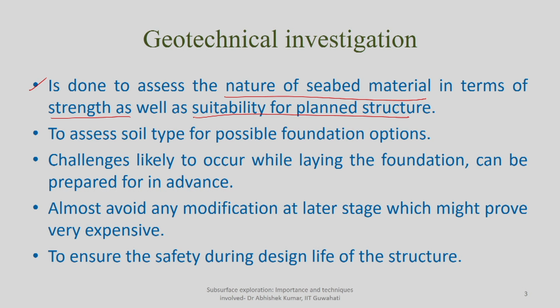Then second, when we go for geotechnical investigation, we also plan to assess soil type for possible foundation options. What are the possible foundation options which are suitable considering the soil type available at the seabed, or at deeper depth also, depending upon your depth of exploration. Then third, geotechnical investigations are also likely to give a clear indication of what kind of challenges can be witnessed while laying the foundation. That is how you can be prepared in advance for those kinds of challenges.